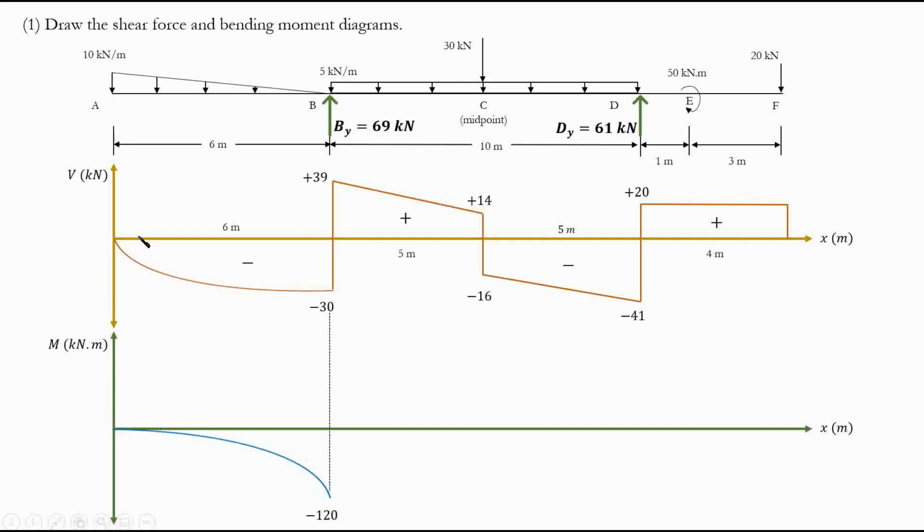Then here, as you see, the value of shear increases, right? In terms of magnitude. It basically means that your slope is getting steeper. So you start with a flat slope, and then your slope increases, and here you have the largest slope because you have a large shear value. Now we're done with this, right? So that's why we draw it like this and not like that. Because if you draw it like that, first of all, your slope in the beginning is not 0, and your slope must be 0. And at the end, your slope is flatter, but that is not the case. So the whole idea is that the value of shear represents the slope of your moment diagram. That's all.